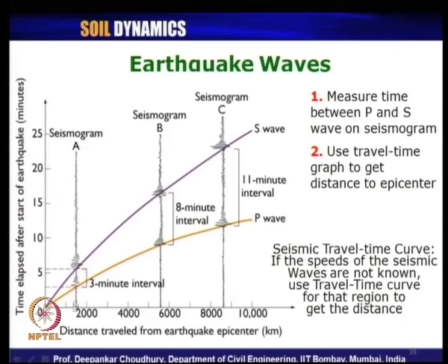What can we do? We can take a graph paper. Now, the distance travelled from the earthquake epicenter is on the x axis and the y axis shows time elapsed after the start of the earthquake. Now, we try to match these 3 locations in such a way in the graph sheet that their distance as well as individual distances between the stations and the time intervals follow a continuous pattern. That can be easily done by changing the positions of those seismograms and their distances.